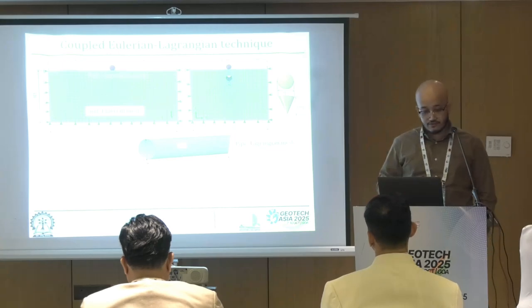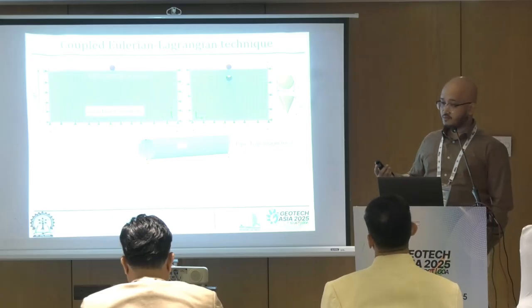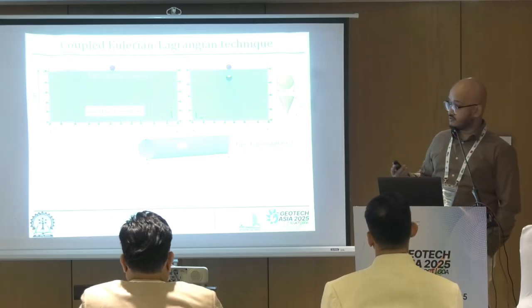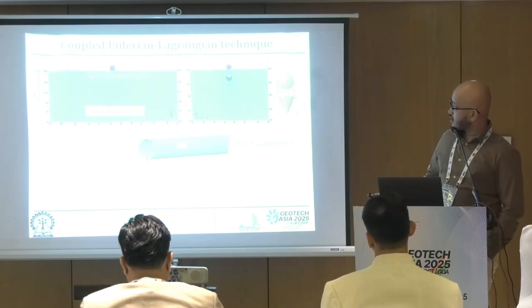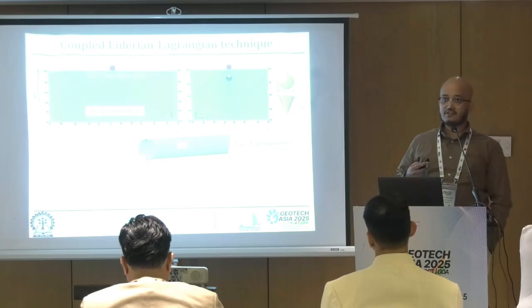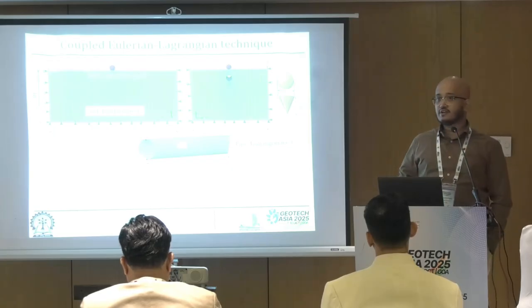Now, if I talk about this very briefly, there are two types of bodies, or two types of parts, that have been used in this particular model. One involves the Lagrangian part, which is the ball and the pipe, where it deforms the nodes that are formed there. So these mesh displacements follow the material displacement. It's like they are stitched together.